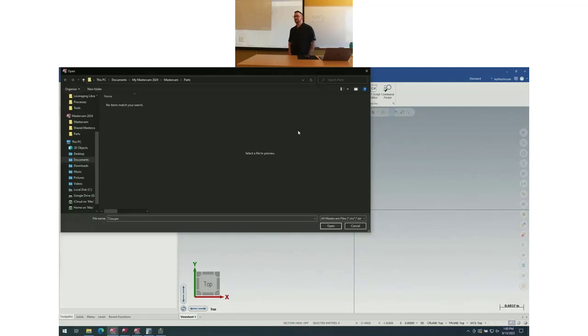Any other questions here? Has there been any work on the hybrid toolpath at all? It seems like it's kind of gone downhill over the last few years as far as its ability to recognize floors. In a lot of cases when we try to detect flats on mold surfaces, where it's conflicting with drafted walls, it really has a problem and starts to error out more often. Okay. So the question was, has there been any improvements or work done towards the hybrid toolpath, noticing some less than favorable results in some situations, especially with the drafted walls, it sounds like.